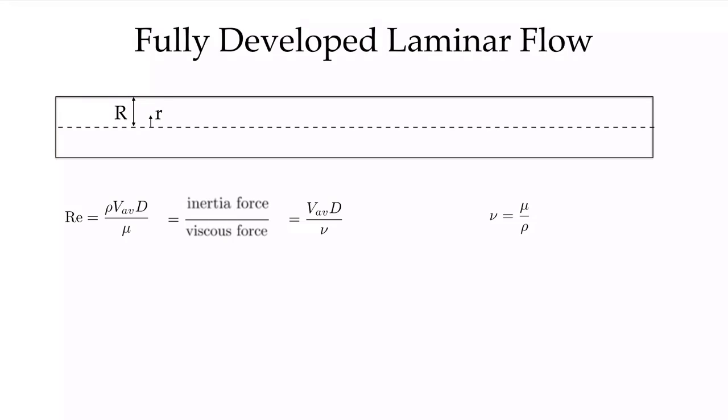And when the Reynolds number is small, the viscous forces will be dominating over the inertia forces, and the flow will be stable and laminar. And we've seen what the laminar flow solution looks like for this parabolic velocity. We'll see it again in a moment. But that is because the viscous forces are dominating. As the Reynolds number gets higher at a certain point, the inertia forces start to dominate, and we start to get some interesting accelerations, velocity fluctuations, which are on the acceleration side of the Navier-Stokes equations, the mass times acceleration side, and the flow transitions to turbulence.